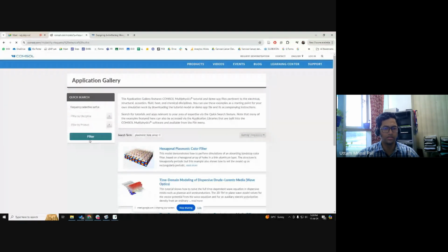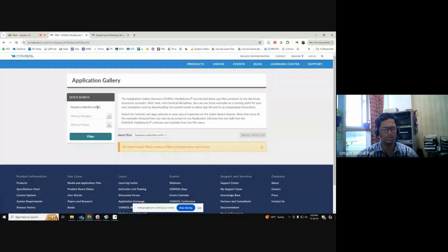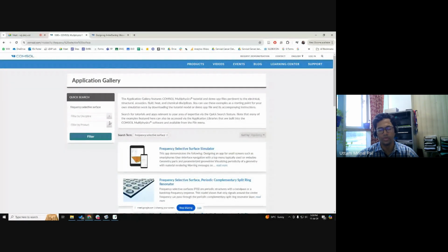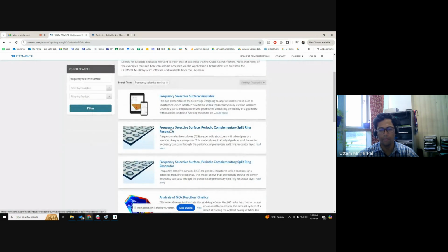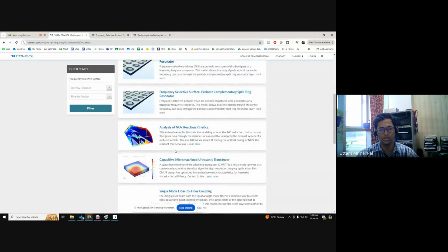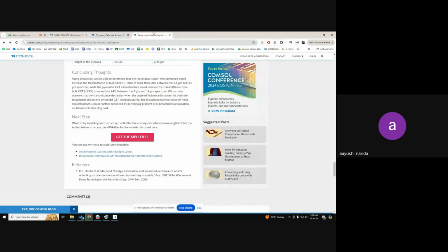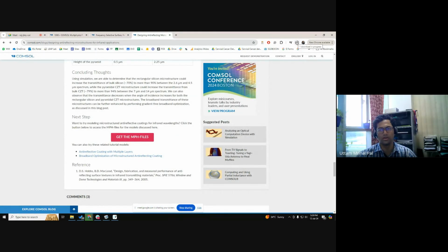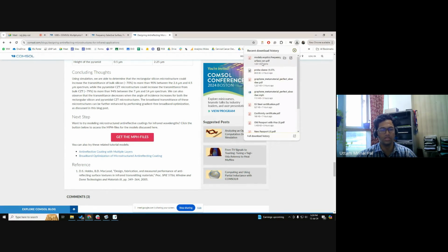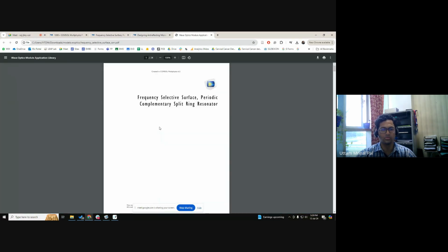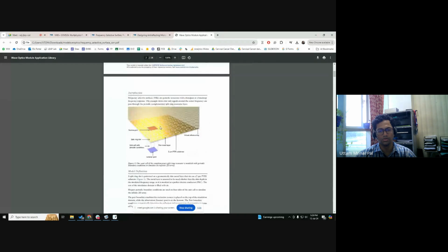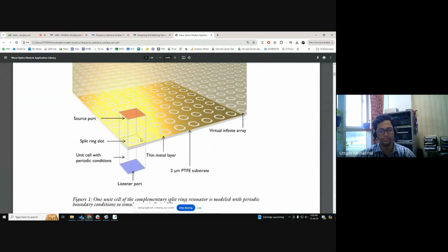The nitride layer, I think, you can model using some glass material. Here you can see this is a case of a frequency selective surface. And we can change its refractive index. It's just the refractive index. You can put the real part and imaginary part, whatever you want to put. You can see if it's available in COMSOL, else you can input whatever you want. So this is a structure you can see, right? This is a slot actually.